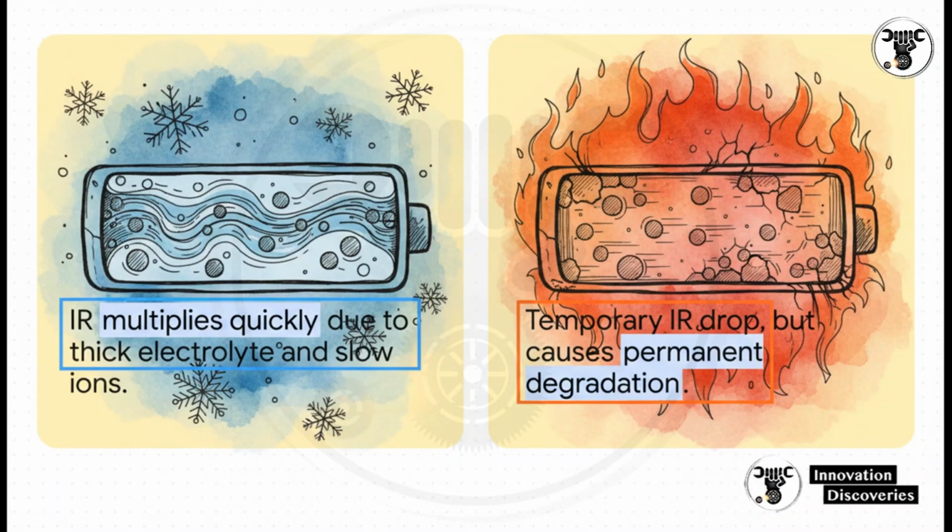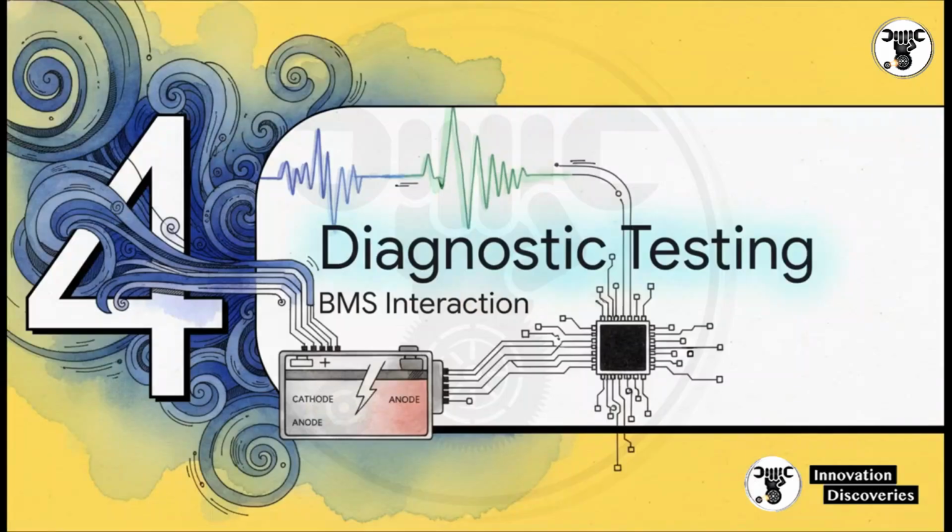It's a crippling effect. If you try to fast charge in this state, you run a severe risk of lithium plating, which will permanently ruin the cell. On the flip side, hot temperatures temporarily lower resistance, making the battery feel super powerful. But it's a trap. That heat is silently accelerating SEI layer growth, electrolyte breakdown, and creating a permanent long-term internal resistance increase.